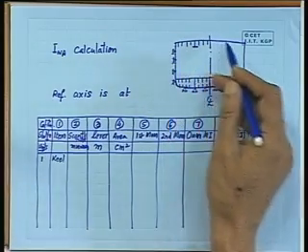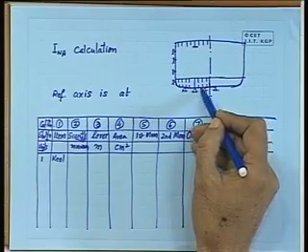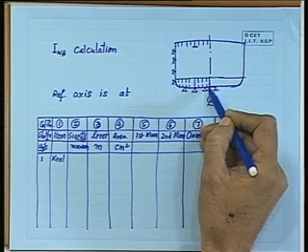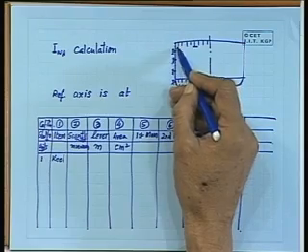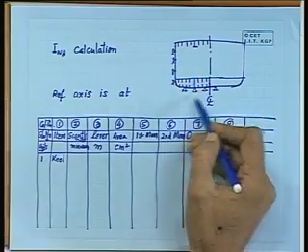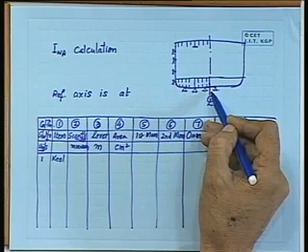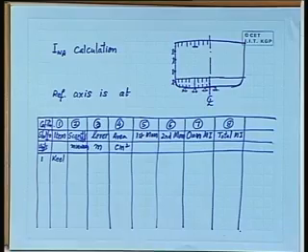And there are a number of such items. If you just consider here, I think it will go into a big list of about 100 items. And for each, because all this may be of the same profile, but the cross section as it is, the things will change because you may have camber, you may have this rise of floor and so on and so forth. So they are not at the same level. The stiffener may be identical, but their lever will keep on changing.